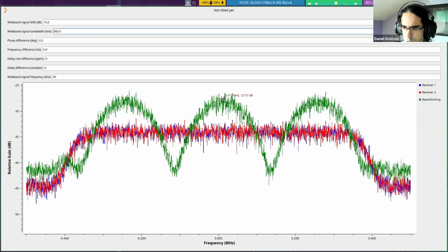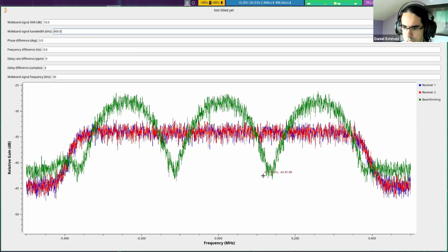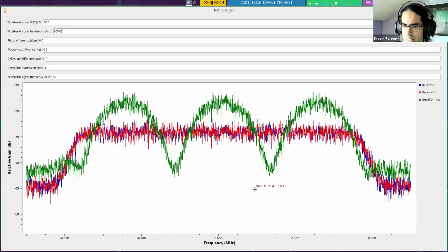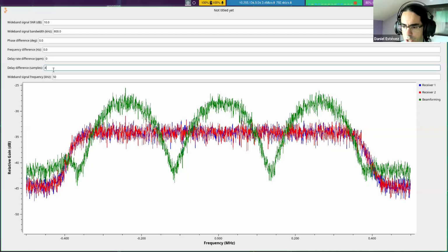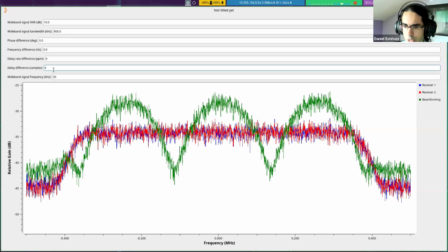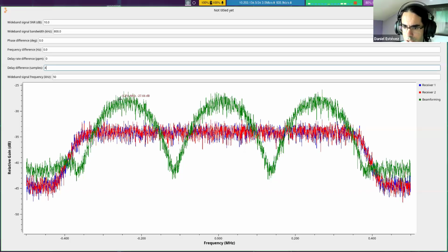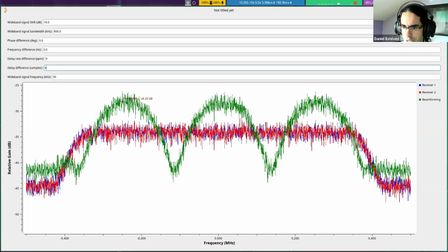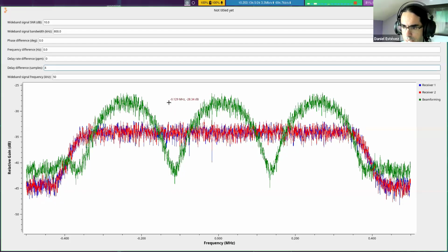constructive interference at some particular frequencies. We get destructive interference at other frequencies. The reason for that is that a delay is equivalent to a phase change which depends on frequency. It depends linearly on frequency. So at this particular frequency, there is a phase change of 0 degrees. Then the phase change increases. Here it will be 180 degrees.